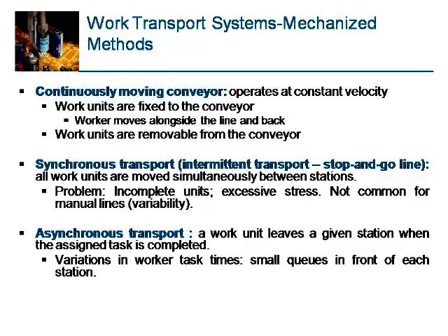The previous workpieces will be moved to the next workstation for the operations. So the transportation is intermediate transportation, a stop and go kind of line. Belt conveyors or roller conveyors or moving finger type conveyors or several other mechanisms are in use for this kind of operation.